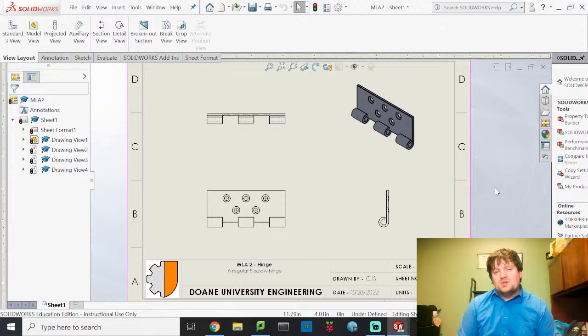Here I'm trying to use good drawing principles where I don't just use dimensions to identify the locations of everything, but I actually use relations. Because by doing so, it allows the drawing to be much more changeable. Rather than have somebody completely redraw this piece from the ground up, they can just change a few dimensions if they need to modify it, or if they want to make a brand new part that's very similar to it, they can copy it, paste it, and then make a few changes to that, and then you have 2 different parts that you have to do minimal amount of work on. Setting up a part that is well dimensioned, that is anticipating change in the future, that is good SolidWorks design.